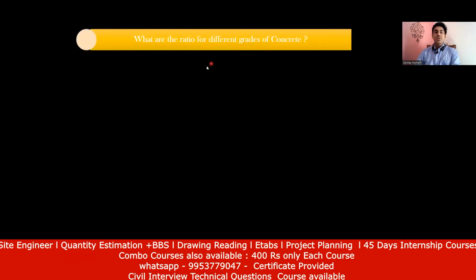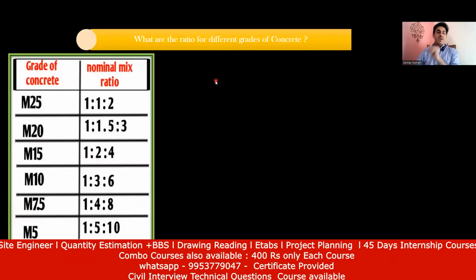The next question you can encounter is: what are the ratios for the different grades of concrete? We have understood that we have different grades like M5, M7.5, M10, M15, M20 and M25. You have to remember M20, M15, M10 and M7.5, right? Quickly try to remember that. If it is M7.5, it is 1:4:8. If it is M10, it is 1:3:6. If it is M15, it is 1:2:4. And if it is M20, it is 1:1.5:3.